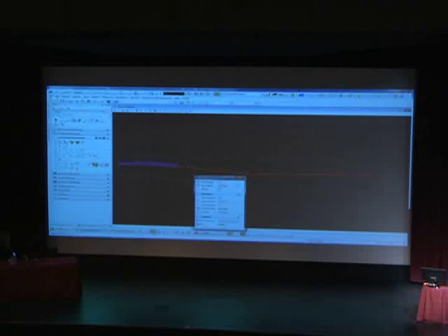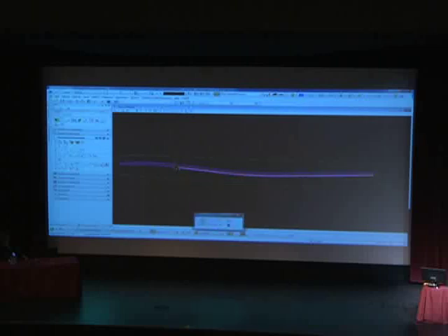All right, what I did was I just used a variable offset taper tool on my vertical alignment, and I transitioned my roadway from an 18-foot roadway to a 30-foot roadway. So let's say I'm tying into an existing road or something. And I mirrored that, so that's why those two blue lines are showing up. I gave a feature definition to them of road edge of pavement, just so that they could be distinguished from my road centerline pavement. All right, and then I went ahead and just completed that offset.